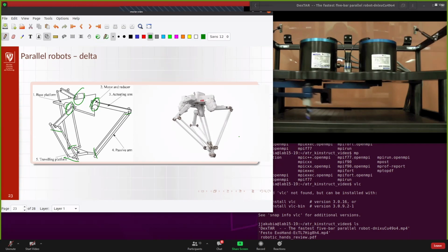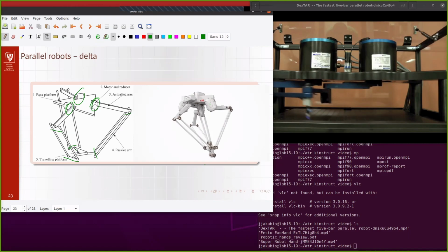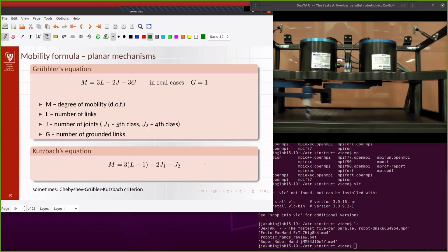As you can also see, how small are the arms that drive this robot. Yes, they don't need to carry the motors. All the motors are in the base. Therefore, they are quite light, and they can move really quickly. When you compare it to industrial serial robots, as you could see in the laboratory, the FANUC or ABB serial robot, you can see that the arms are much lighter in this case. And that is why we get the higher speed.